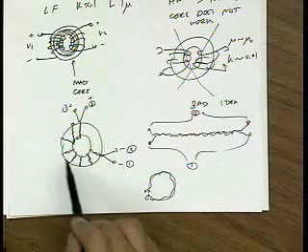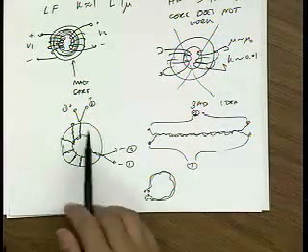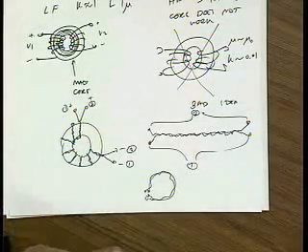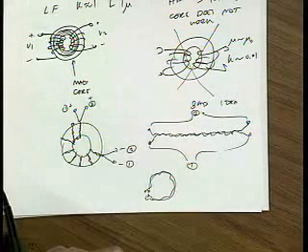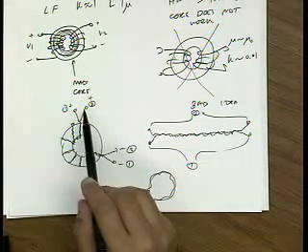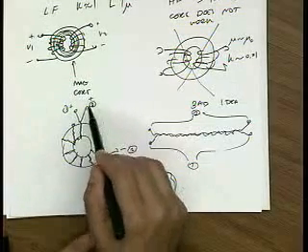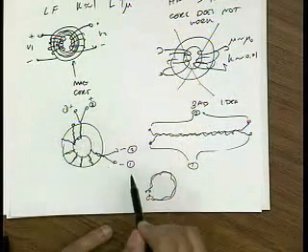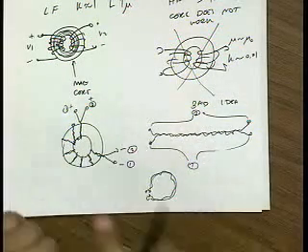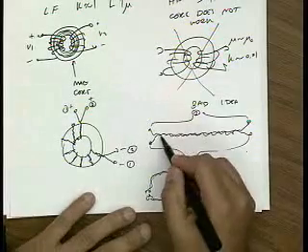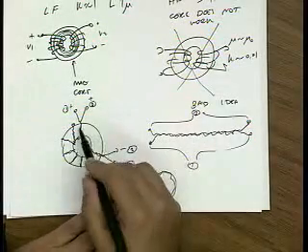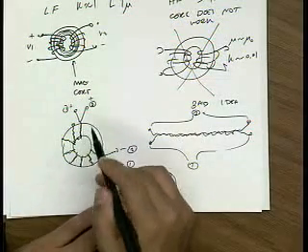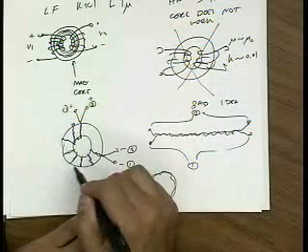So you might ask, why use this core, right? It's not doing anything for you. Well, it turns out that the core is useful because it can reject common mode signals. Let me explain that very briefly. If I send in a differential signal, that means that current 1 and current 2 are out of phase, then the actual magnetic flux produced by this circuit is very small because these are twisted together, very close together, and the flux area is very small. So differential signals generate a very small amount of flux.